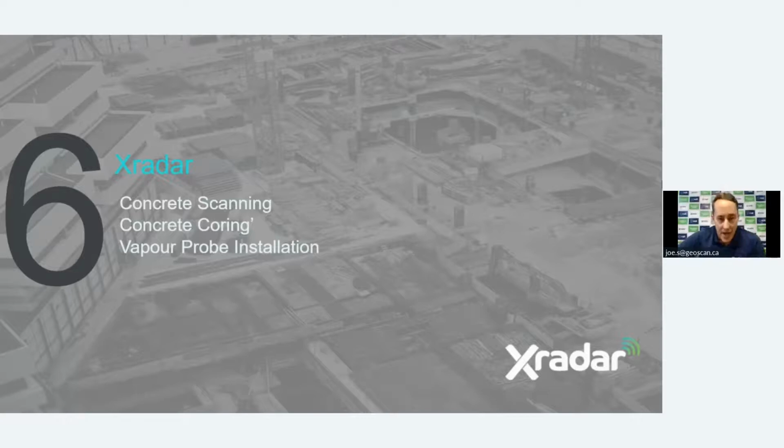Something else that I've found that's relevant is concrete scanning, and especially for indoor boreholes. You must ensure that you scan or image the concrete in a warehouse, for example, or a building before you look to drill through it, because it can often house electrical cables, radiant heating lines, and various other objects. So it's important to do similar due diligence on the concrete as it is with the ground, the general subsurface, for utilities.